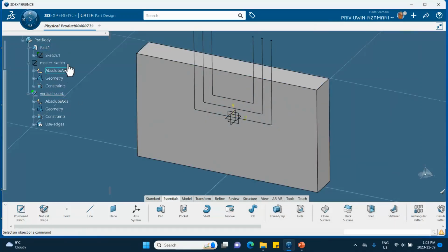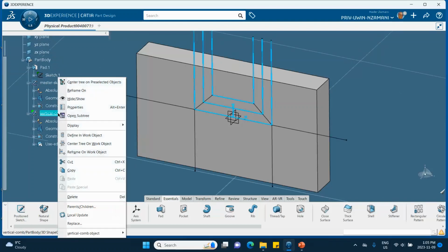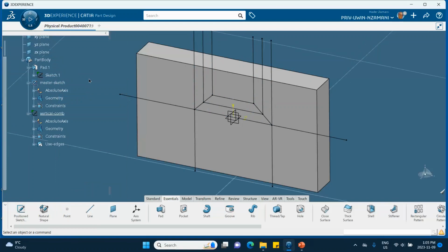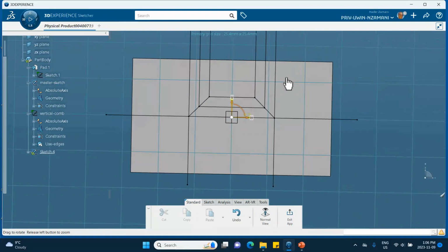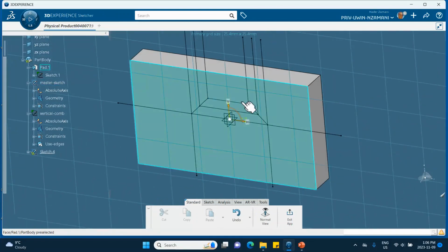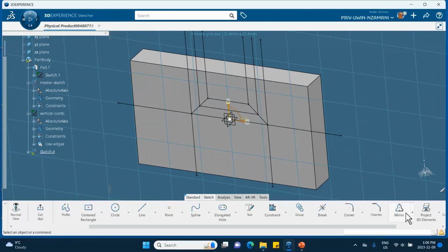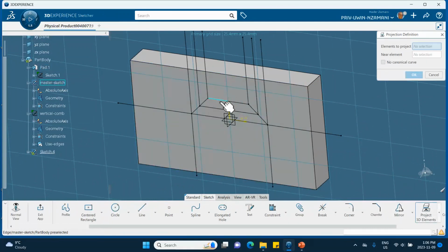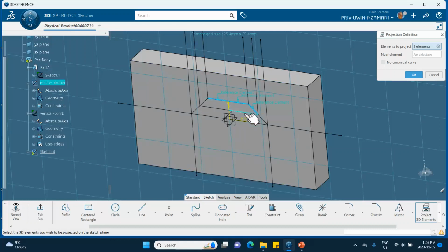So I can actually hide that guy, bring the master sketch into the show, hide the vertical one. There, this is a master sketch. So on that vertical plane, I will sketch, and now project the upper trapezoid. So sketch, then project here. So I want this guy, that guy. Now the slanted ones.